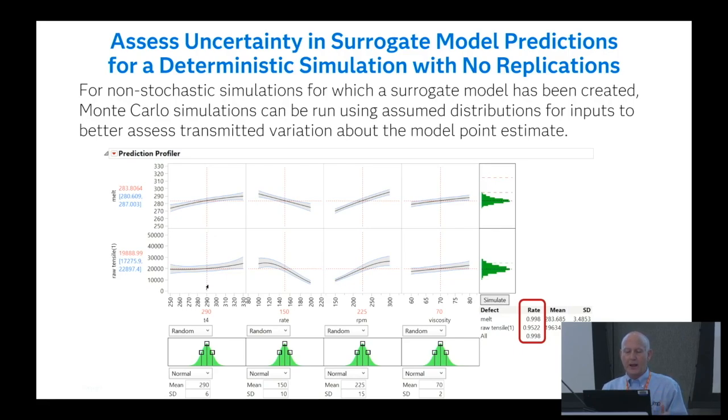I do want to point out that JMP has built into that prediction profiler we've been showing you all day an actual Monte Carlo simulator where if you have knowledge of the variability on the inputs, so down below here you can see I've got the 4 bell-shaped distributions. They don't have to be just normal distributions. There's about 15 different types. It can even be sampled from a data table where this is just historically, we've done this, for years. If you just randomly draw from that data, you can mimic the variability on the input.